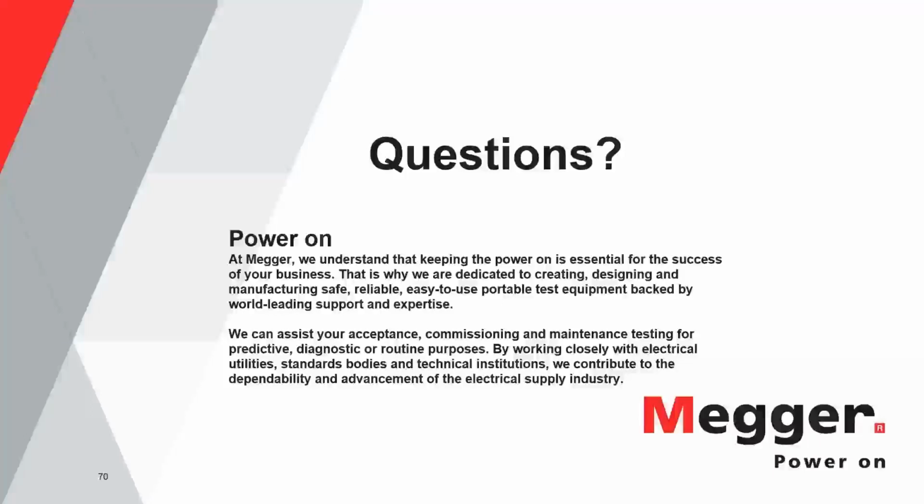most of the time on a three-phase fault, and the three-phase fault is typical mainly on the generation side. So when the fault hits you guys on generation, that's really going to shake your transformer. So that's one of the things that you have to keep in mind. So this does apply to you guys. And remember as well that most of the transformers that you have in your facilities are designed maybe as shell type and are pretty robust.